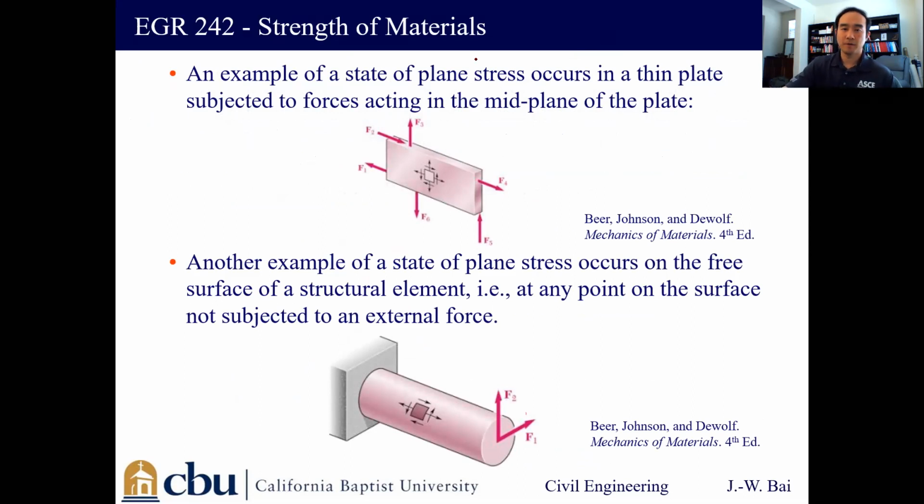So let's say here we have a plate and we have applied forces all around here. And these forces are all applied in the in-plane direction, not the out-of-plane direction. Out-of-plane direction means this way, okay? Then we can think about all the stresses as parallel or perpendicular to the xy axes only, not about the z axis.